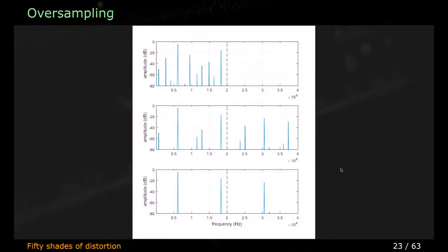So what we can see here is what happens if I have a sine put through a waveshaper with a lot of gain, with oversampling and without oversampling. As we can see on the first table, there are a lot of contents everywhere, and the worst part is that all the extra peaks are not related at all with the frequency of my input sine.